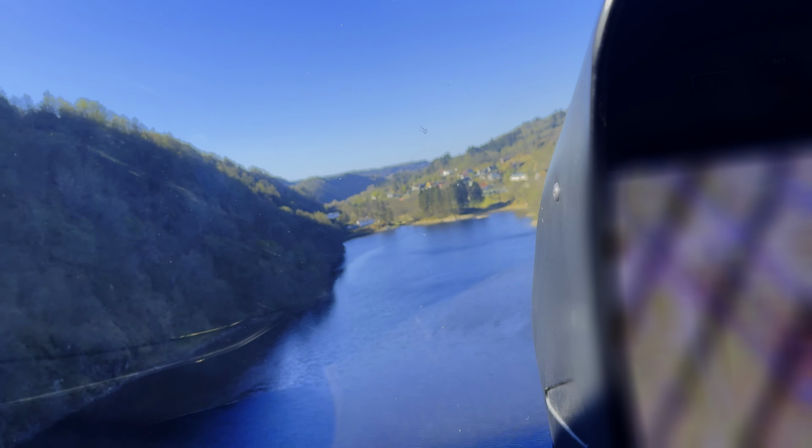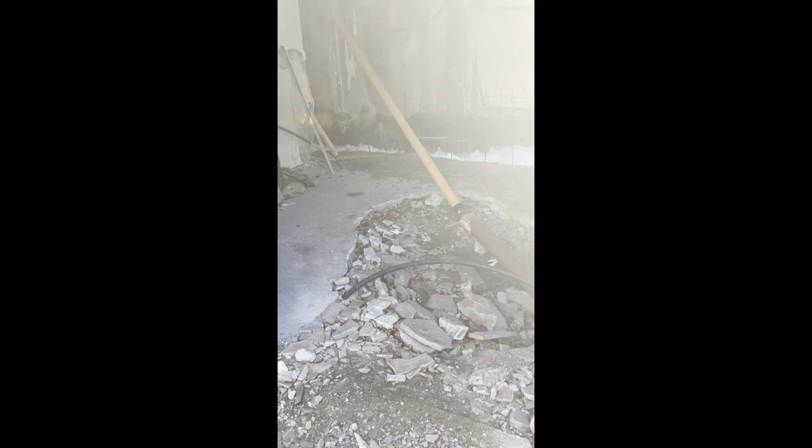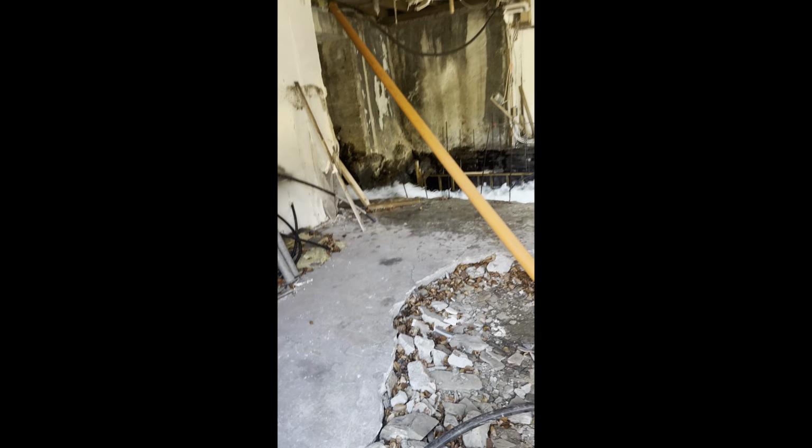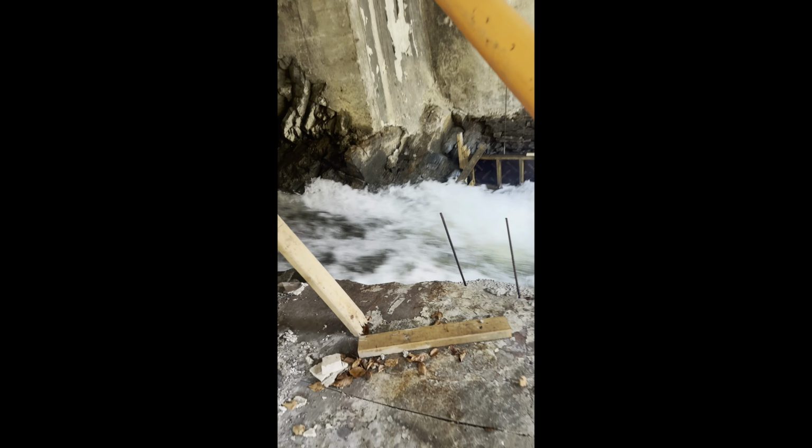Our site is the extreme end of this. 4.8 meters of fall, the height of about a 2-story house, with about 2,500 liters of water flowing per second. That rules Pelton out, and it's even too low for Francis, but it is possible to achieve with a Kaplan turbine. So that's what we built, and here's how to go from the hub out.